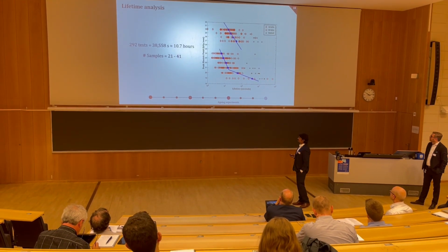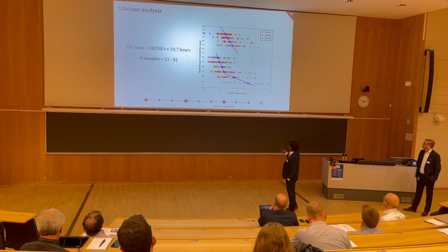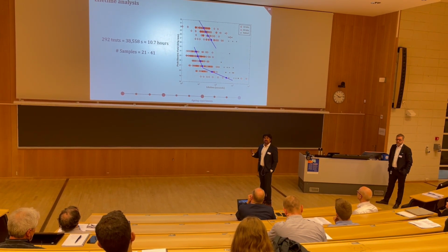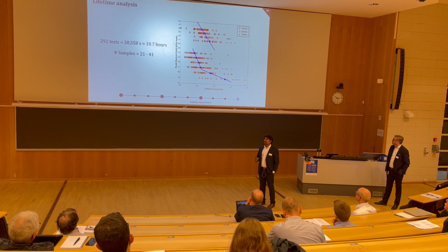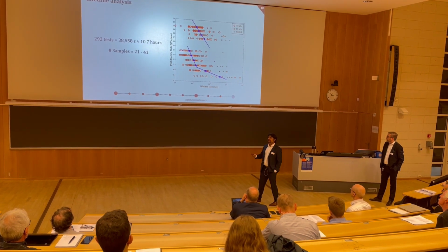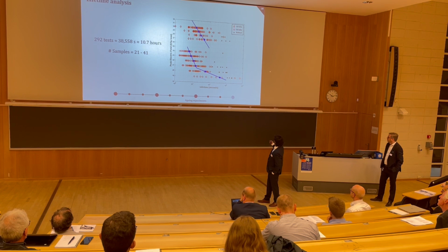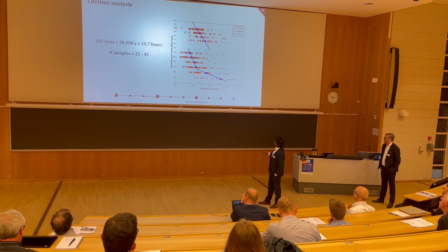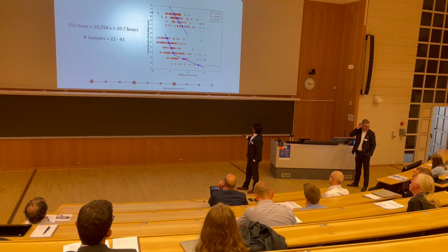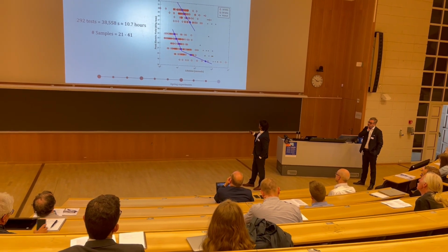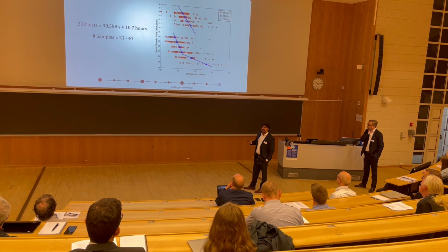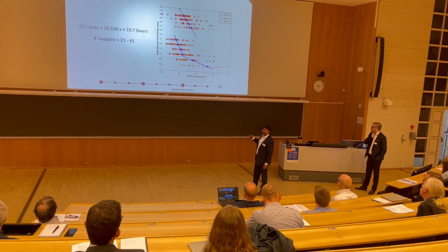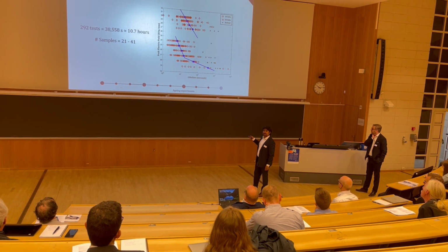Right. Okay, thank you for the question. First of all, we do include the censored experiments as well in the median. The reason for this is there is a chance that there can be insulations which have a breakdown somewhere, and we have to include them in the statistical distribution. About the possibility of this transition point even being there, we need to populate this area and make sure that this point is actually where it is.